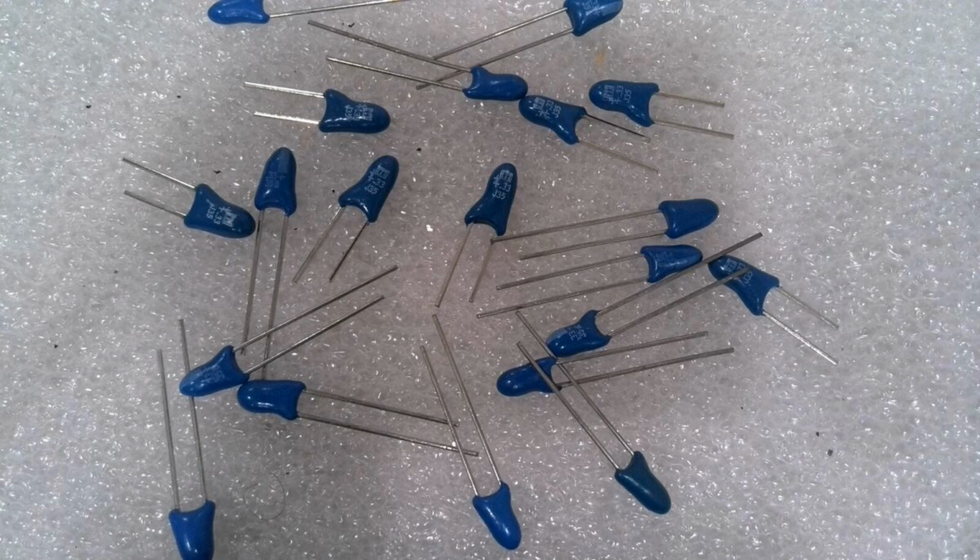2. Polarized capacitor. Polarization means that the capacitor has specific positive and negative terminals, anode and cathode. It must be connected with the correct polarity in the circuit. If the polarity is reversed, the capacitor can break down, leading to failure or even a short circuit. This is because the dielectric layer, tantalum pentoxide, is designed to handle electric fields in one direction.